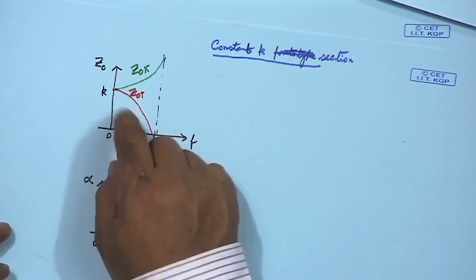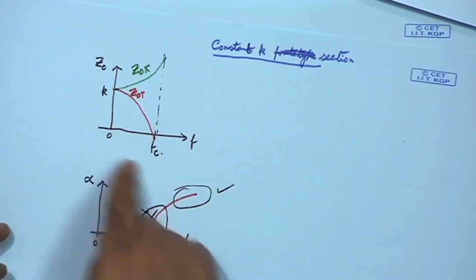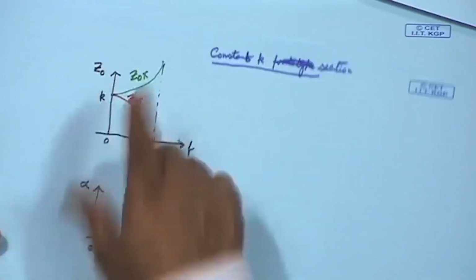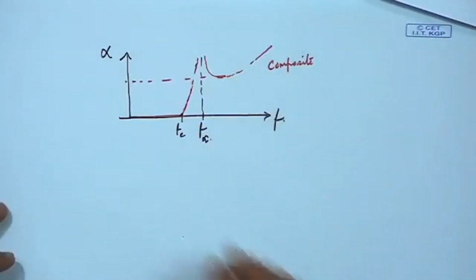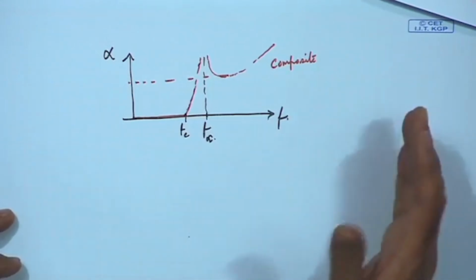because we have enforced the m-derived section to have the same Z naught variation as the constant k. So, the characteristic impedance problem I have not solved, the m-derived section has not solved this problem, but what people do then to match the section, there are some extra matching sections at the load end and the source end that they put. So, that makes this whole filter a bit bulky. So, that is the problem with the image parameter method, but something is done,